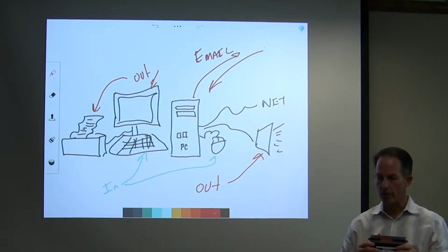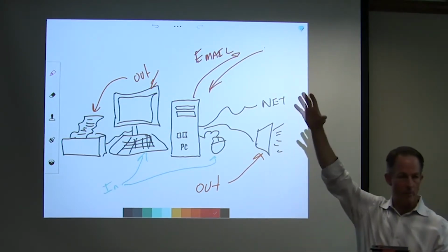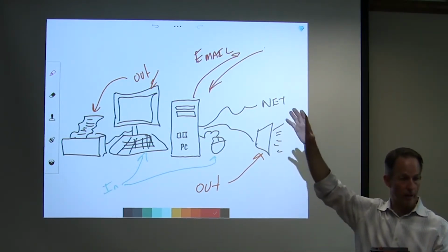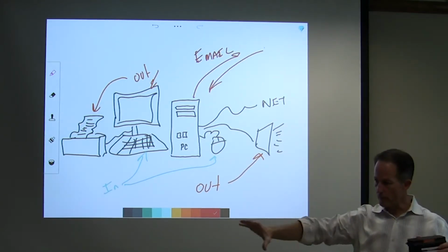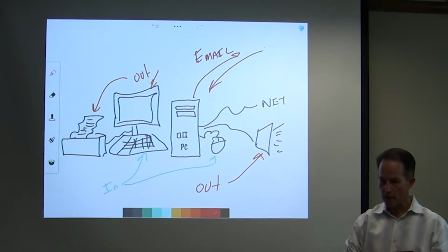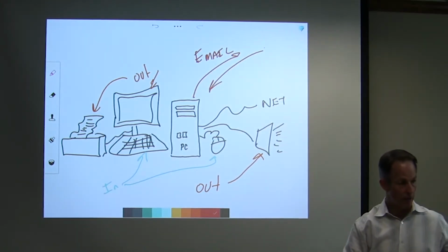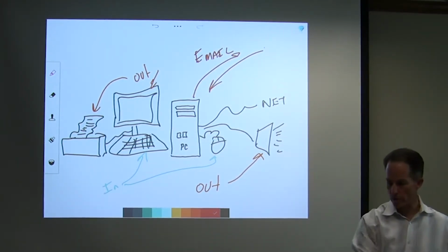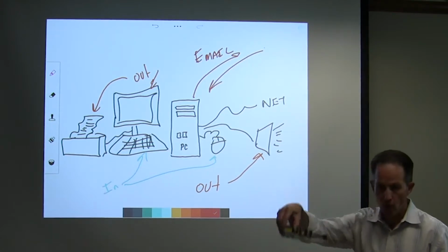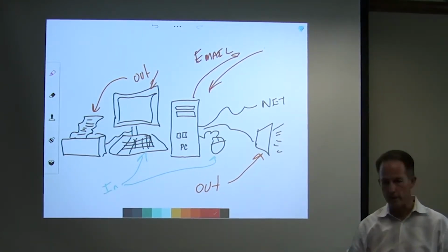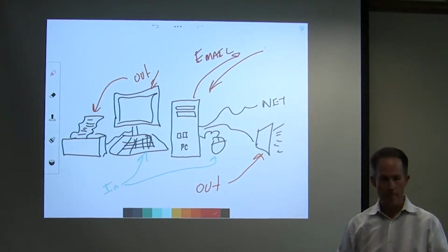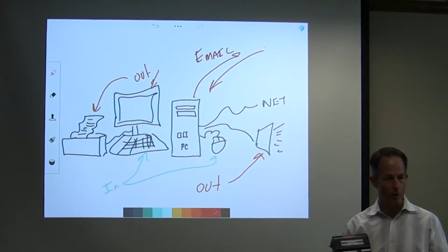We have a supervisor, which would be a computer that manages the Jaces. So it's like the director level, right? And it's collecting all of information from managers, which are then collecting information from the individual unit controllers, our VAVs, or our air handlers, or fan coils, unit heaters, whatever it may be. Okay. Does that make sense, how that works?